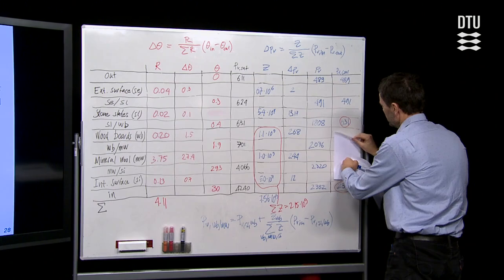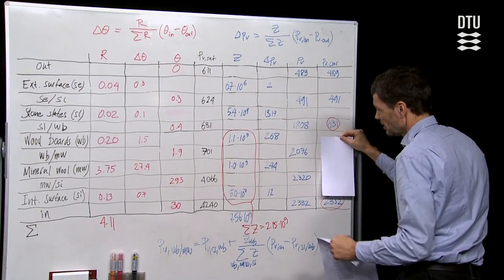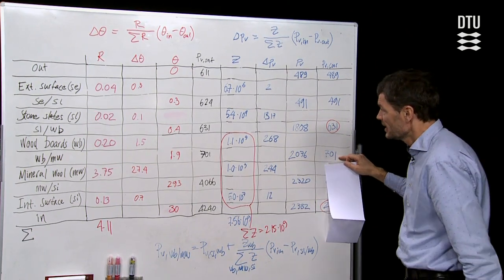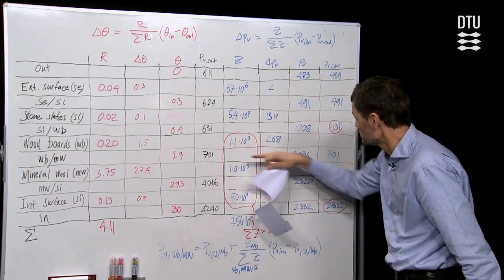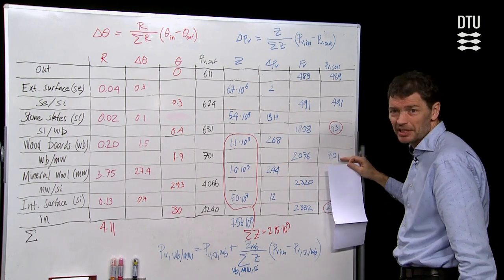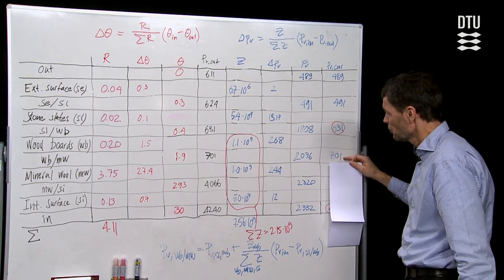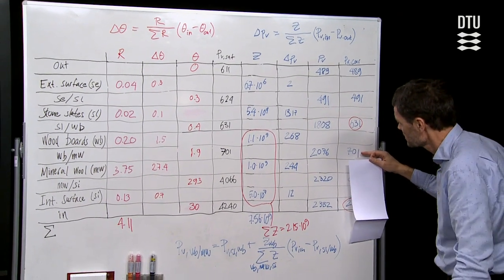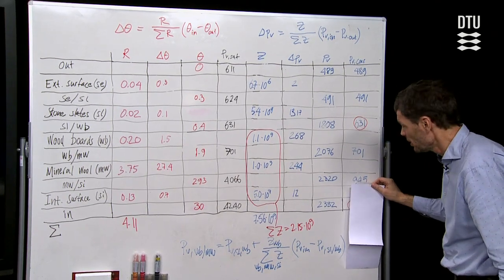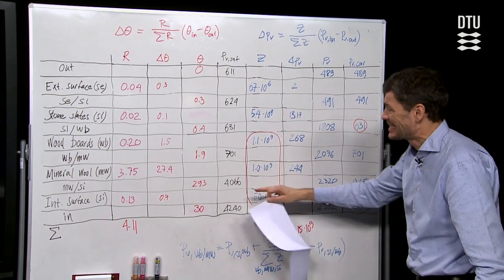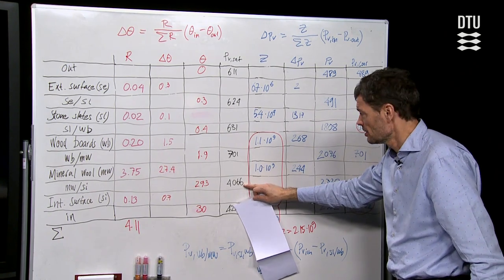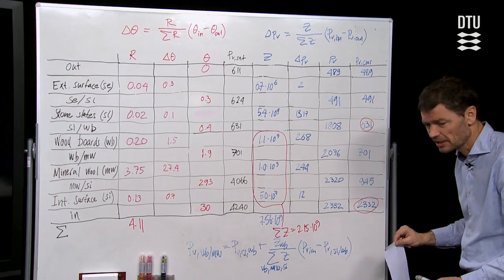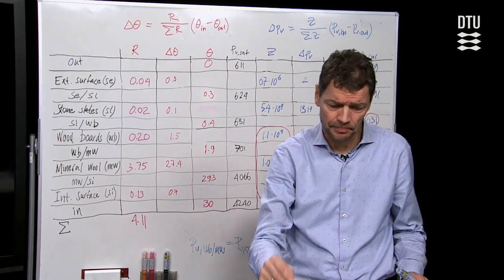So that becomes my calculation to calculate delta P over the wooden boards. When I calculate that extra, then I get 701 in that position, and that is, well, that's still at condensation. So I get a higher value, but it cannot be more than 701. Next, when I do the same calculation for the next, then I get 945, and 945 is less than 4,066. So this is good. And this way we can keep calculating all the way towards the interior.